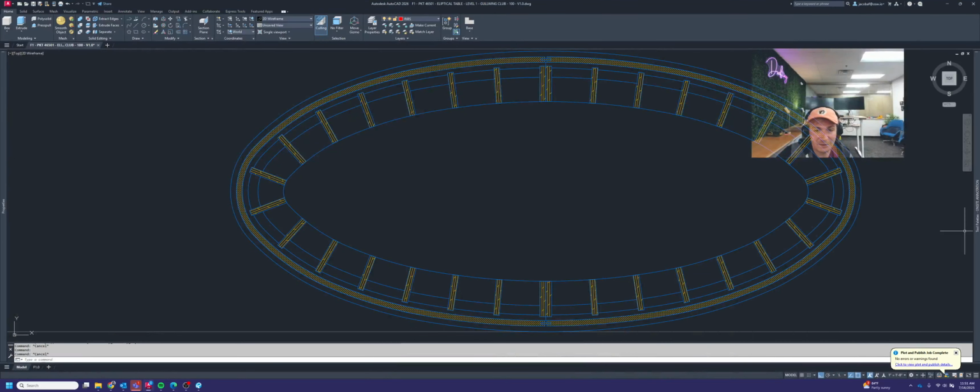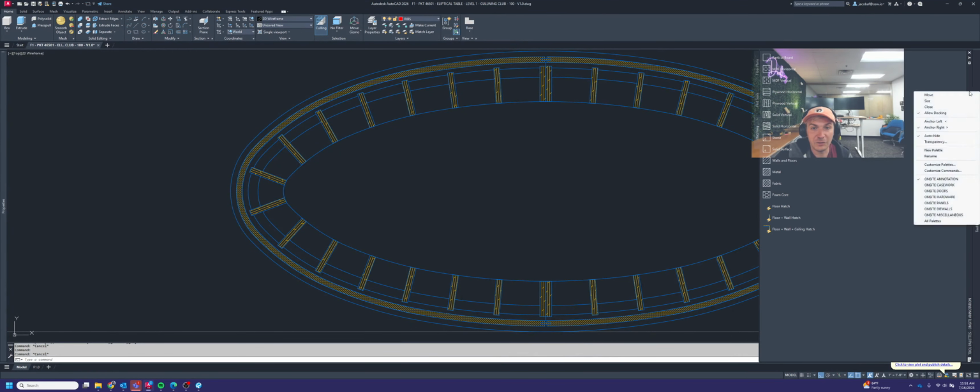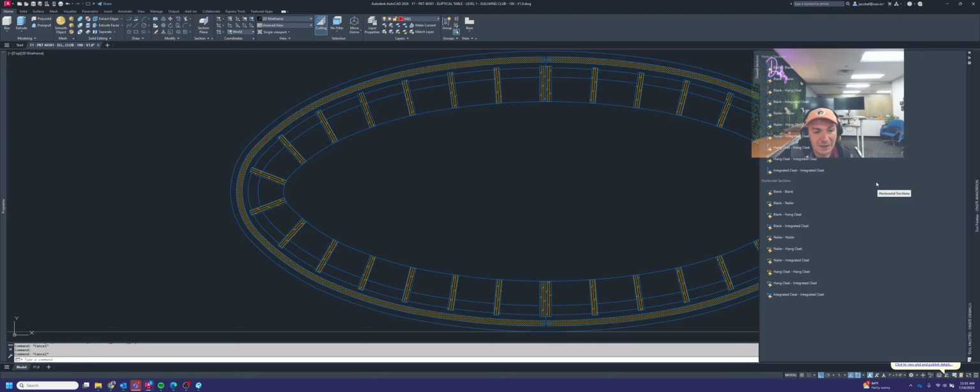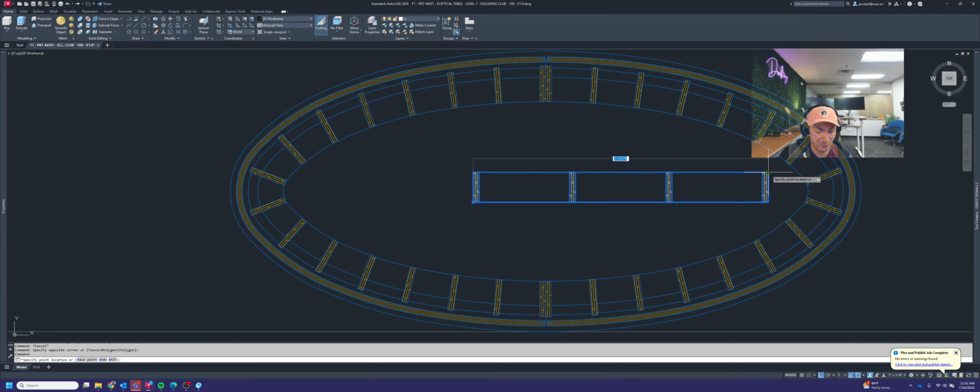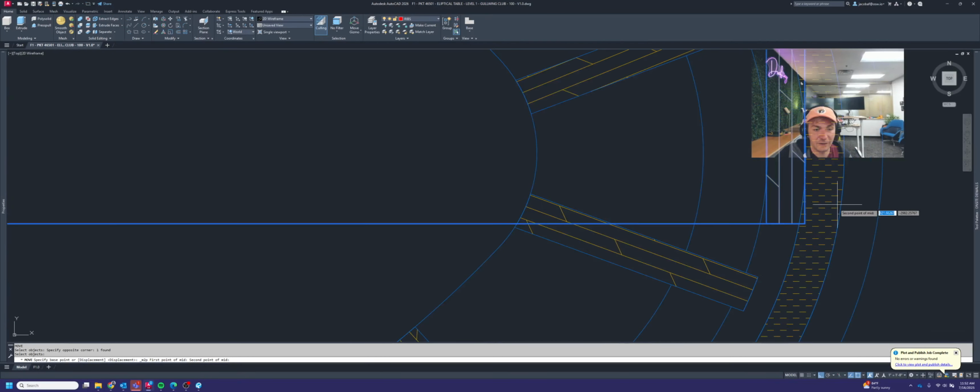And when we do that, we do have some standard die wall areas that you can add to your drawing nowadays. I briefly looked at them earlier with you, but there are vertical sections and horizontal sections that you can add to your print. We'll add a horizontal section of a die wall here in the middle when it loads. These are more complicated blocks, so they take a little bit of time to populate. Let's start with making this 4 feet wide, 48 inches, and see what that does. And I'm going to place it dead center of the table.